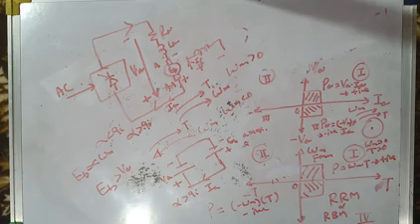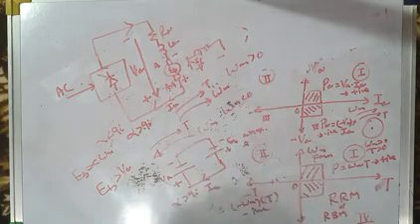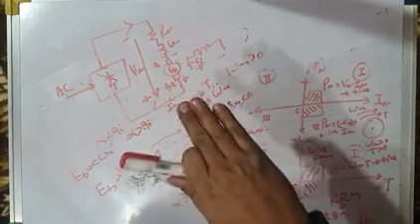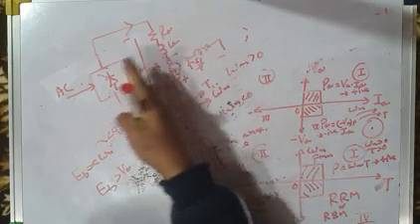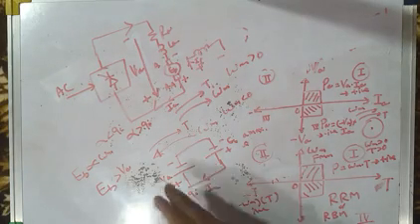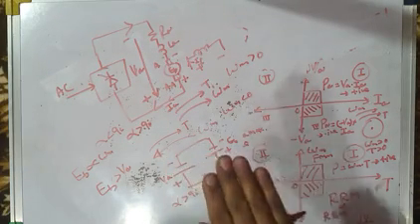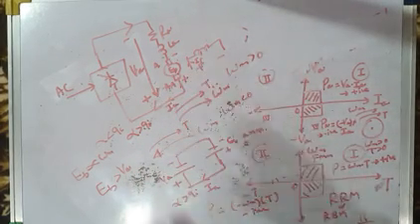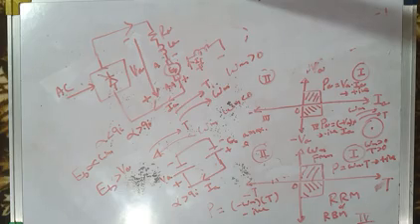Negative power means our machine is not operating as a motor, it's operating as a generator. And as a generator, it is converting the mechanical energy of the crane and the motor into electrical energy, supplying that electrical energy back to the source and saving the energy, and simultaneously applying a braking torque and slowing down the crane so that the crane comes down slowly at safe speeds.